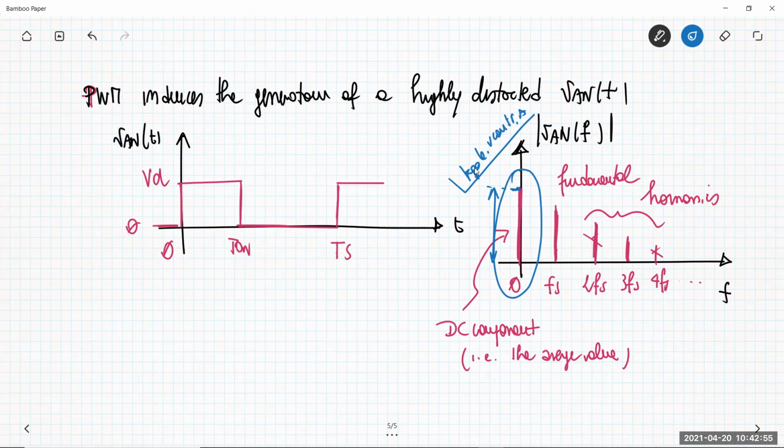So this means that this process started with a modulation, a pulse width modulation specifically, where the control voltage is compared with a triangular waveform. The information that is in the level of the control voltage is employed to generate a specific value of the duty cycle, which in turn induces a distorted voltage waveform.